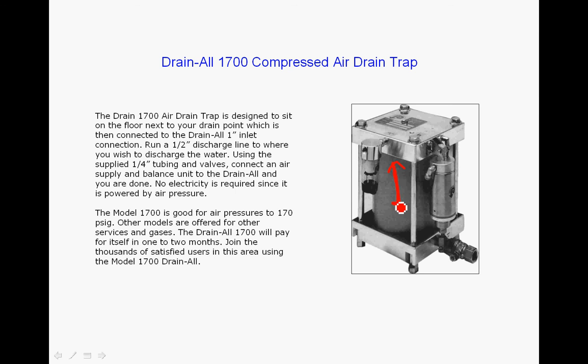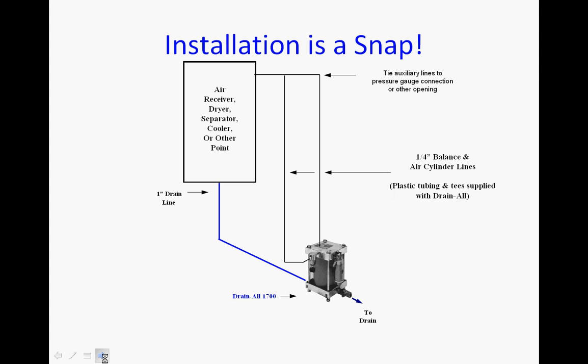And it utilizes a magnetically operated float which goes up and down. As it rises, the float acting magnetically operated valve snaps open an inlet air supply, which is what powers the unit, and that in turn opens up an air cylinder and a 1-inch ball valve, and all the material is discharged from the system, and it just does a great job. It's simple, reliable, and very easy to install. You just literally set it on the floor, and it'll probably outlast you at the amount of years it puts into your plant by causing virtually no trouble. It's a great product, and we use it all the time.